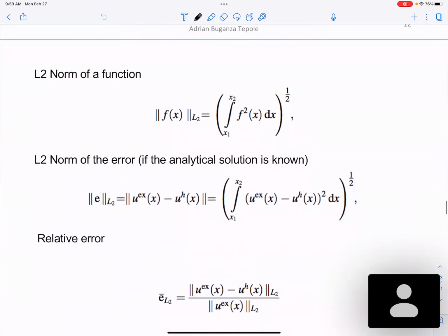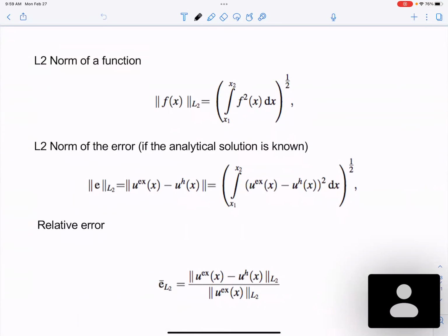What do I mean by convergence? The idea is that as you refine the mesh, we kind of explained this a little bit when we were introducing the weak form. Depending on how your mesh becomes thinner and thinner, if your weight functions become sharper and sharper, you should get more and more the strong form.